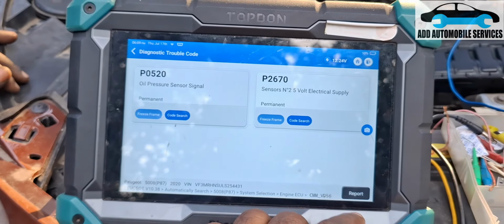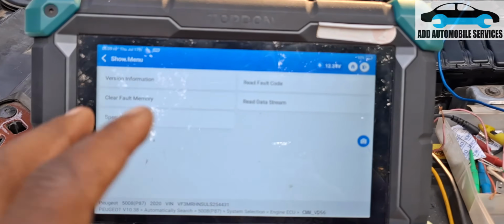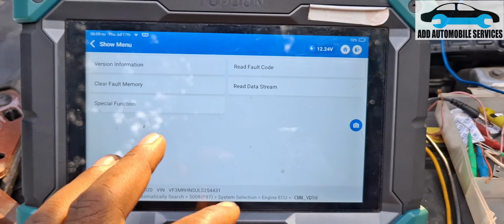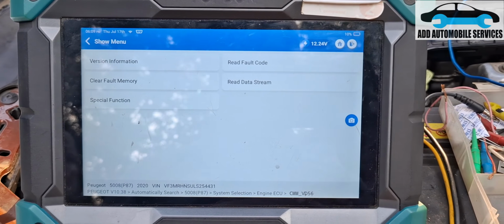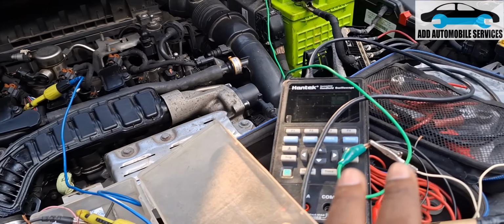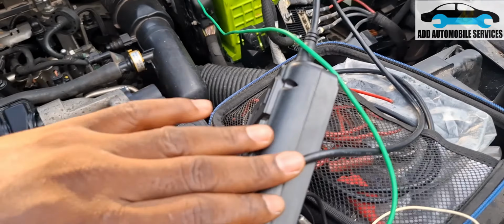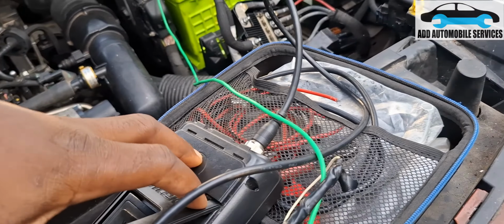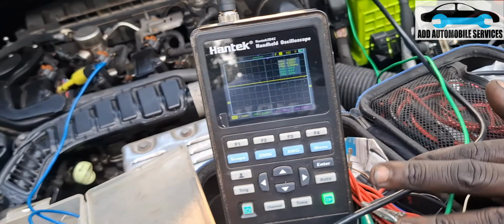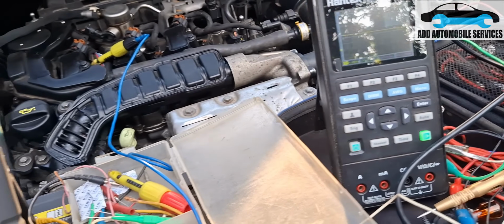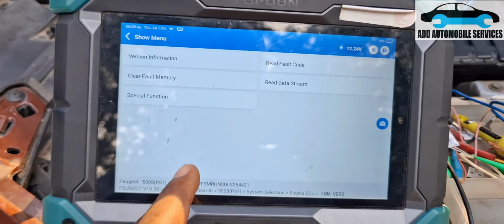For me to verify that that's the signal line, because I don't have access to a wiring diagram to know that brown is ground and red is signal, I have to do this manual testing so I can identify the ground and the power, and see if I can tell the client that it is a sensor issue or a signal issue. Moreover, they've changed 2 sensors already. That's why they called me.